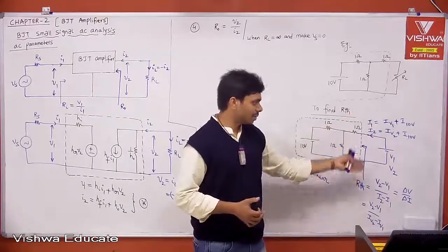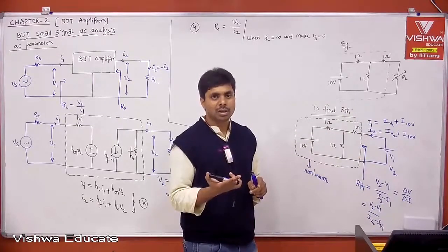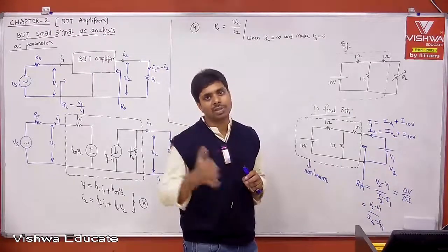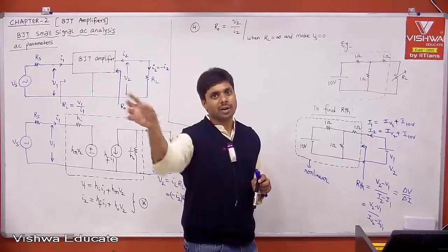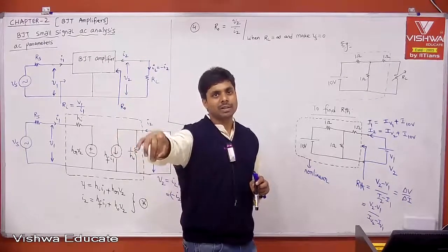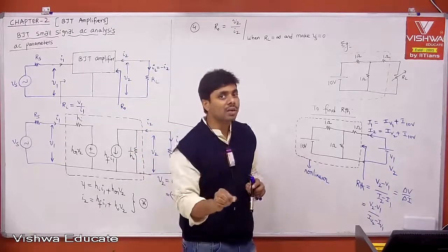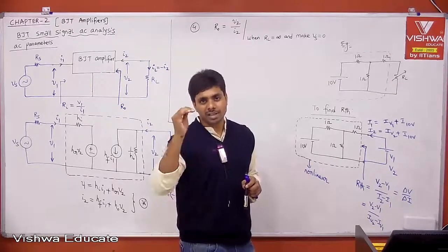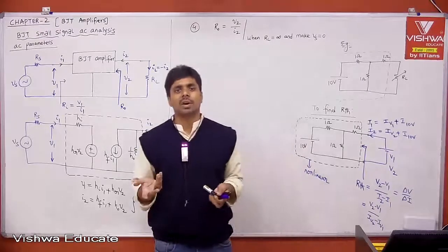Then we go with the dynamic definition like V1, V2, I1, I2. And I told you that BJT is non-linear, MOSFET is non-linear. That's why I already gave you the summary before starting our BJT small signal AC analysis. I told you ID1 is because of VGS1, ID2 because of VGS2, and ID2 minus ID1 because of VGS2 minus VGS1. If there is any common quantity, that will be cancelled. Therefore, if there is any DC quantity, we don't bother. I told you that point, right? As we go on, we will understand. If there is any DC quantity, that will be cancelled. Then we don't need it, avoiding unnecessary complexity in calculations.